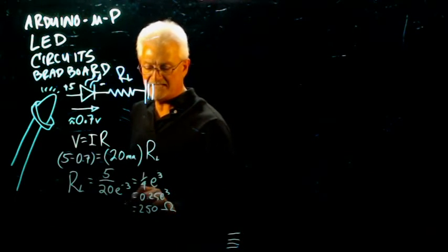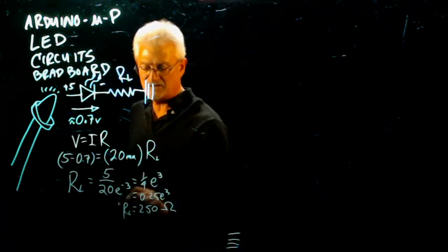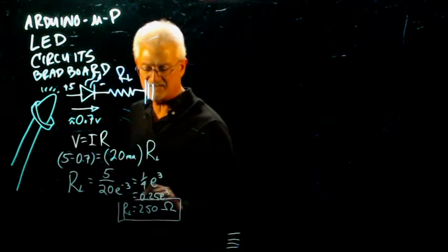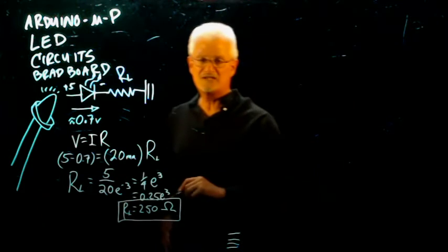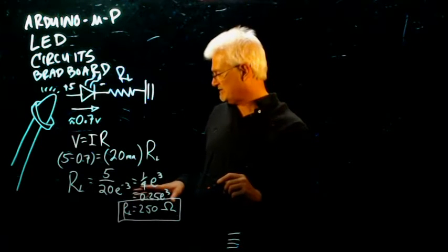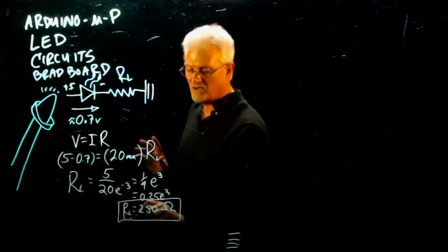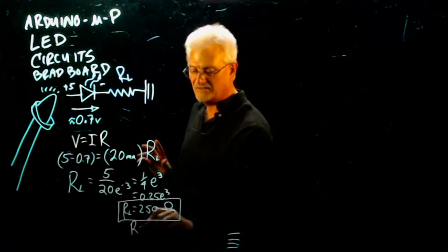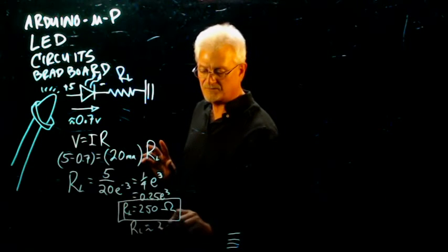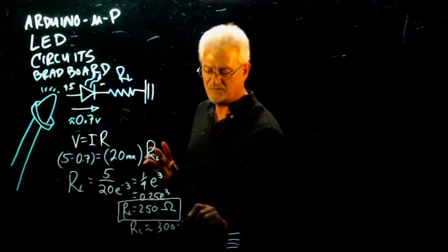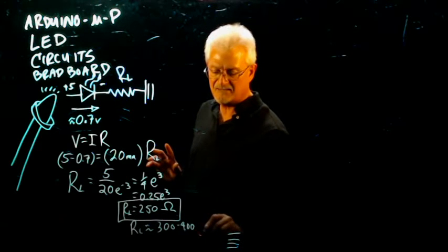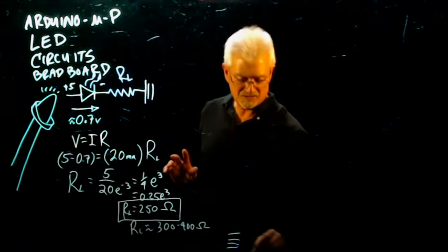Okay, so nobody cares. The current limiting resistor is kind of an estimate. If you're really trying to get as much current as you can through there, you might go ahead and do an exact number here. But also nobody really cares if you have a current limiting resistor on the order of 300 or 400 ohms. That's going to be okay. All of those will work just fine.